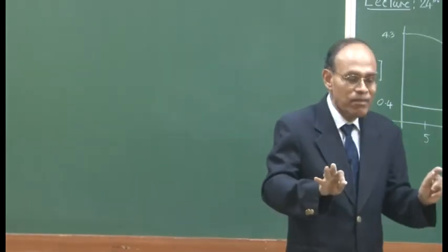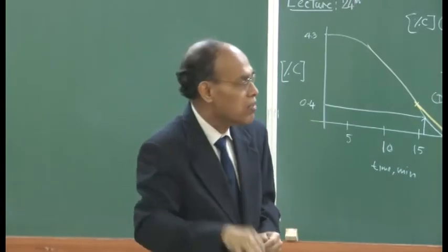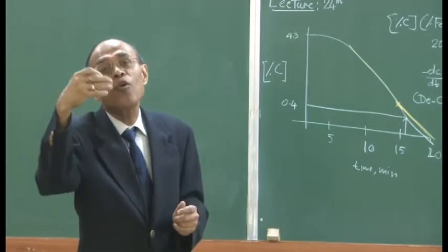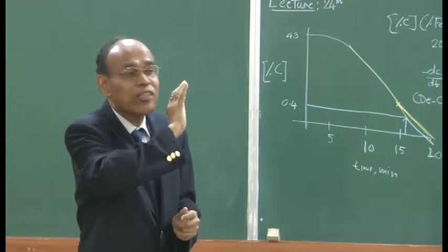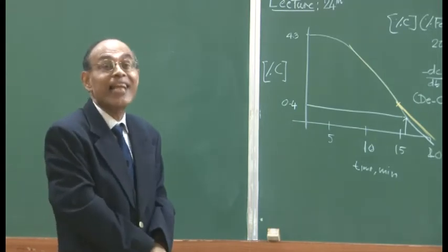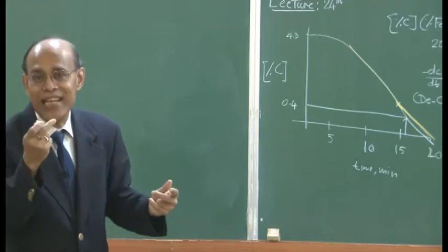So, thermodynamics of oxygen steel making need not be discussed. You have silicon, sulfur, phosphorus, manganese, and you put in oxygen, they are going to be all removed. So, there is not an iota of difference between the various versions of the oxygen steel making process. It is the rate; the blowing period may get reduced because the efficiency of stirring has changed now.